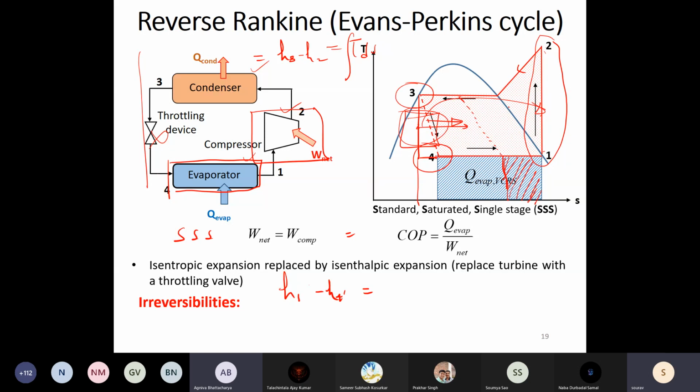Only when it goes to extremely large capacities, do you see the cost benefit of putting a turbine of, let's say, which is generating 50 kilowatts or 100 kilowatts of energy, and driving a compressor which is probably consuming 1000 kilowatt. So there you may see a benefit, because that 100 kilowatt, that could be a cost effective system than having an expansion device for 10-20 watts of recovery.